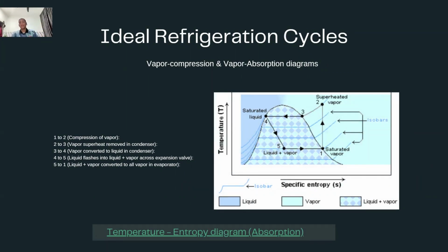Between 1 to 2, as we said, the pressure of the refrigerant increases. Then it is slightly cooled from the superheated to the saturated vapor, while it remains constant till point 3. And the pressure also remains constant while heat transfer occurs when heat is released from the condenser to the surrounding area. And the enthalpy and the entropy from 3 to 4, as you can see, remain constant here. So the temperature, yes, is reduced back to the temperature before compression, but the enthalpy and entropy remain constant.